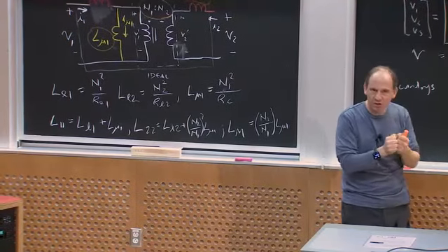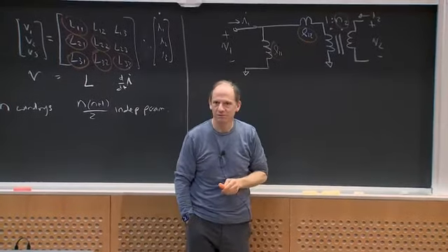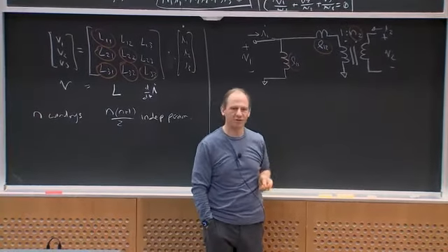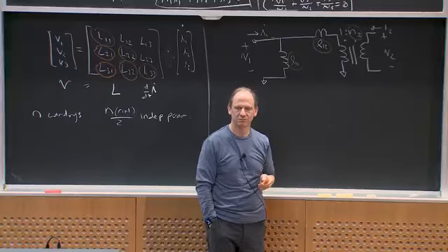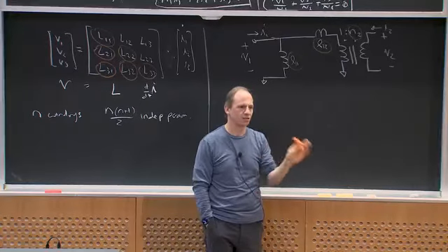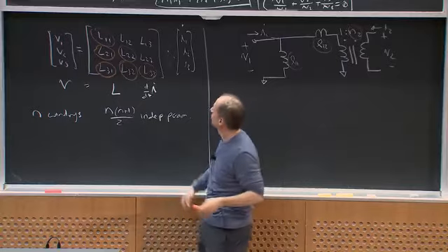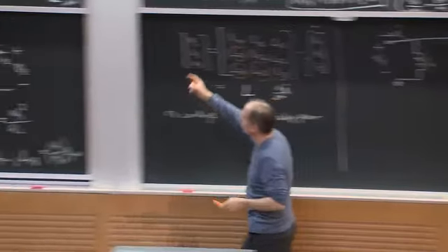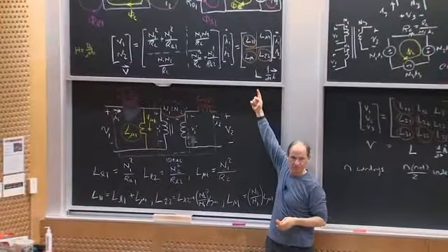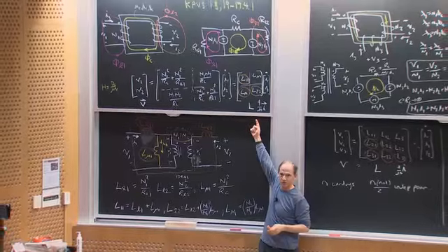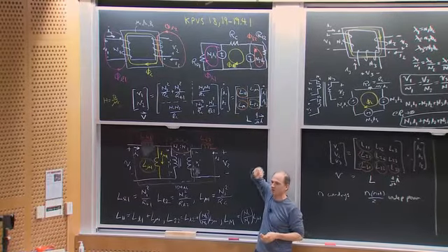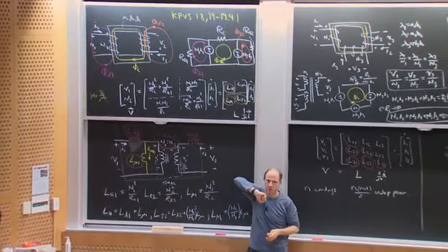So you can easily get some negative inductance value in your model if you're not using a physical model, all right? Don't get concerned if you see that. That's just because you're trying to pick parameters to really match what the inductance matrix description does. Whatever those circuit parameters turn out to be, you'll get the right inductance matrix description.